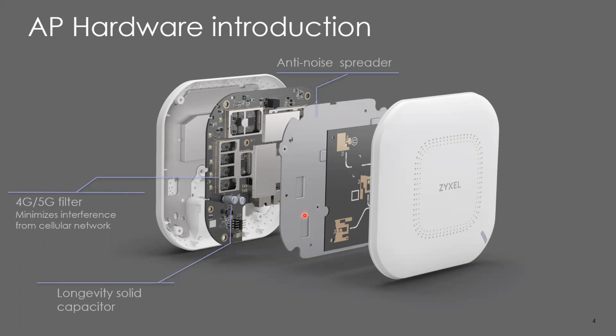It's not going to give you a big difference as far as general range or coverage goes, but this little bit of difference that you get by moving the antennas off the PCBA onto their own board really helps you out on those marginal cases, those users that have a low quality connection. It's the difference between something that's barely usable and something that's slow but solid and steady.